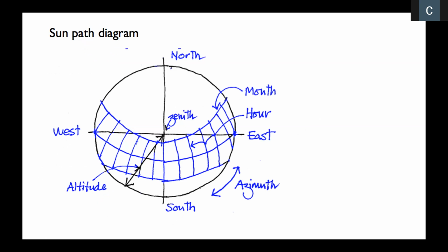Here is an example of a sun path diagram with all the pieces labeled. You've got, on the one hand, the zenith, because this whole black circle here is a projected sky dome. The center point at the crosshairs is the zenith, which is directly above your head if you are standing at the point of interest for which you are drawing this sun path diagram.